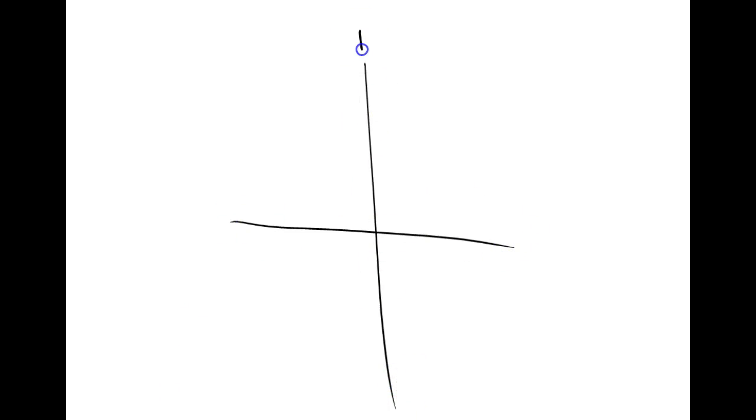So we have what we call the forward direction, the forward bias direction. So what the VI characteristic curve is going to look like. This is I, and this is IF forward biased, and this is IF reverse biased, right? And this is VF right here, and we call this VR, so that's voltage reverse biased.